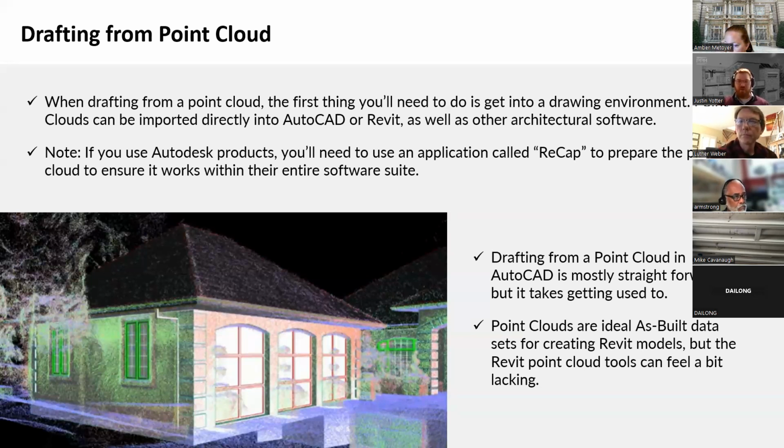Drafting from a point cloud in CAD is pretty straightforward, but it does take some getting used to. There are lots of options in CAD to color, slice, crop, move, and rotate the cloud in different ways. And you'll need to use the view cube to regularly adjust your UCS orientation to properly work within the cloud in different positions.